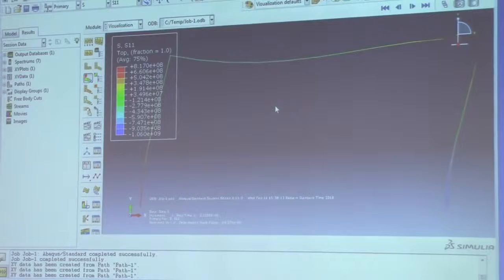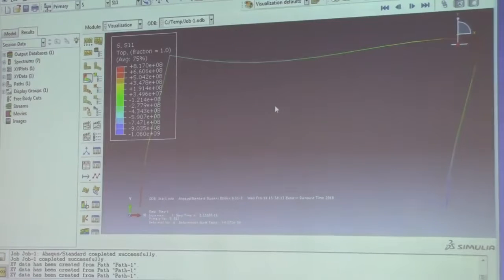And another question is that I already said at the beginning, for different loading conditions, sometimes one element is enough. Sometimes we can only do an approximation because Abaqus for beam problems can only do a cubic polynomial.